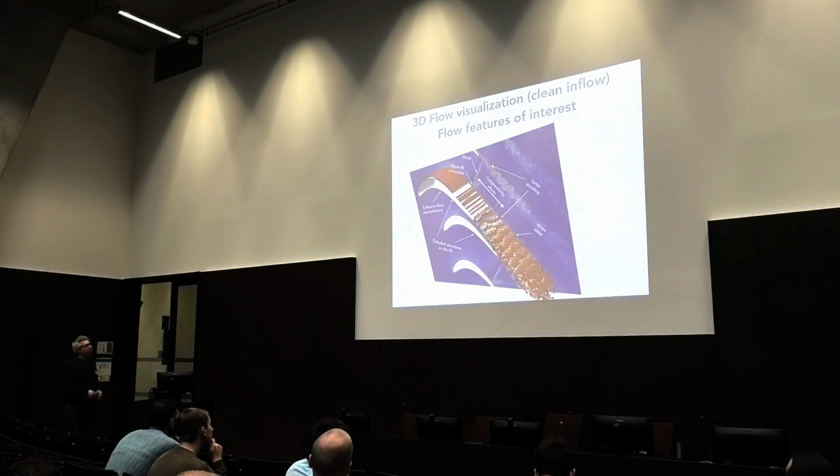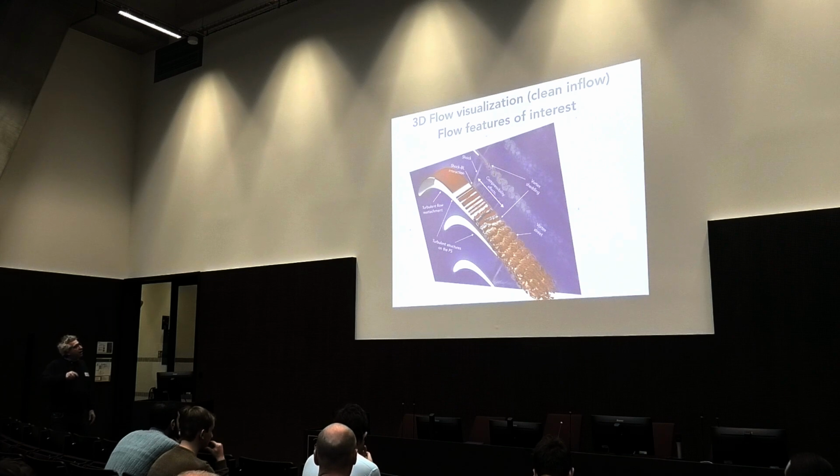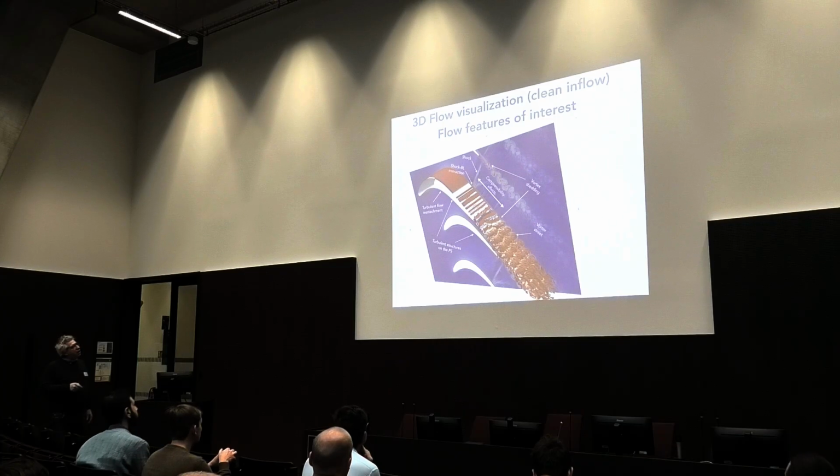So now I will show some movies, and what do you have to observe in this movie? So this is typically the blade cascade. We reproduce the blade cascade of the von Karman Institute. You see that the blades are not located like in a real aircraft engine on a circular ring. They are disposed linearly in a cascade. And what we see here is the vorticity, the vortical structure. You see here the boundary layer in red. This boundary layer is subjected to instabilities. These instabilities grow, and then here at the trailing edge, you have a shear layer and you have vortex shedding